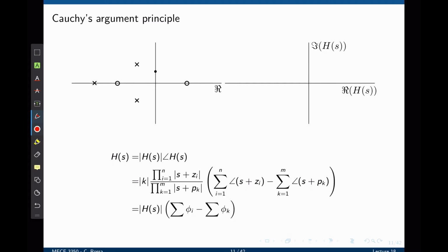To find the phase and magnitude of the transfer function, we can now trace lines from each pole and each zero towards that input frequency, and now evaluate the phase and magnitude of each individual pole. Let's assume, for example, that the magnitude of this zero is z1. The magnitude of this zero here is z2. The magnitude of this pole is P1, here we have P2, and the third pole we have P3. The magnitude of the entire transfer function when subjected to this specific input frequency is Z1 times Z2 divided by P1 times P2 times P3.